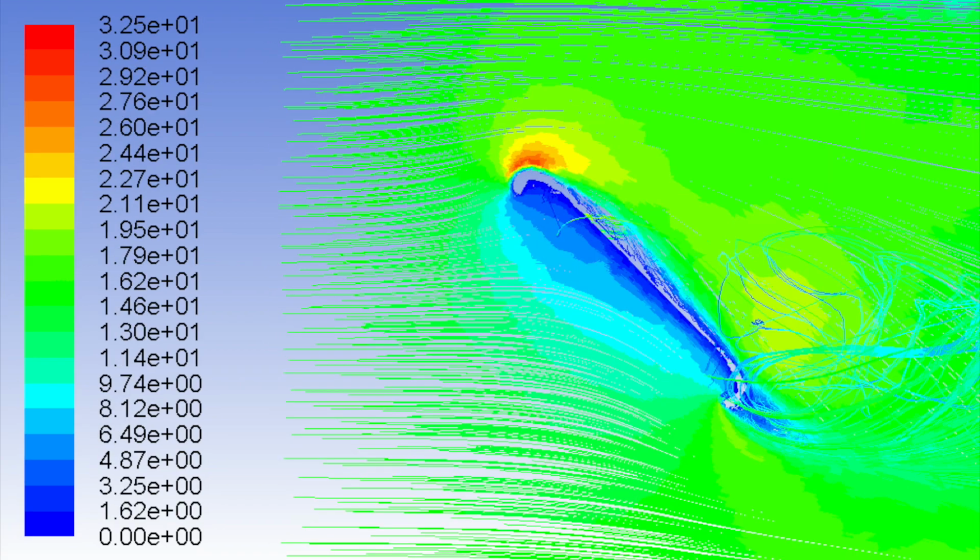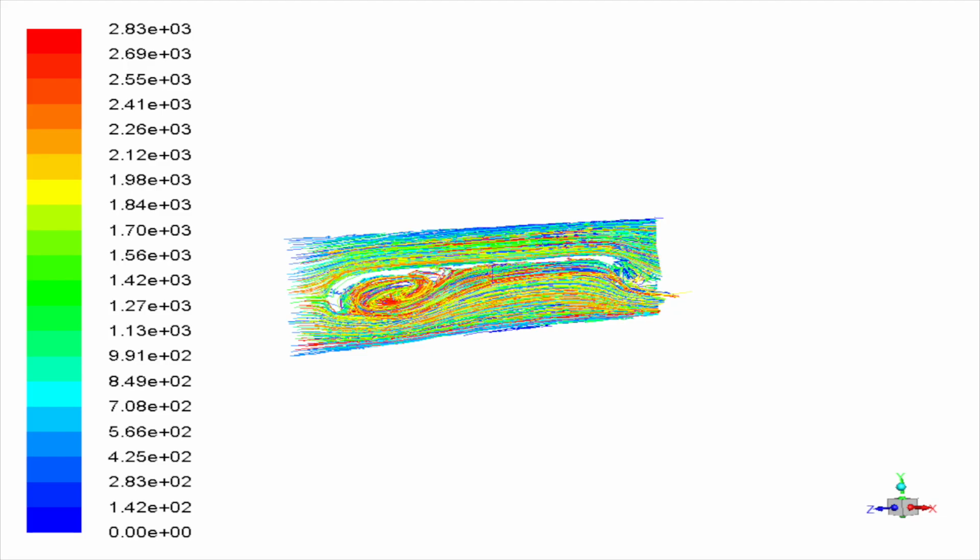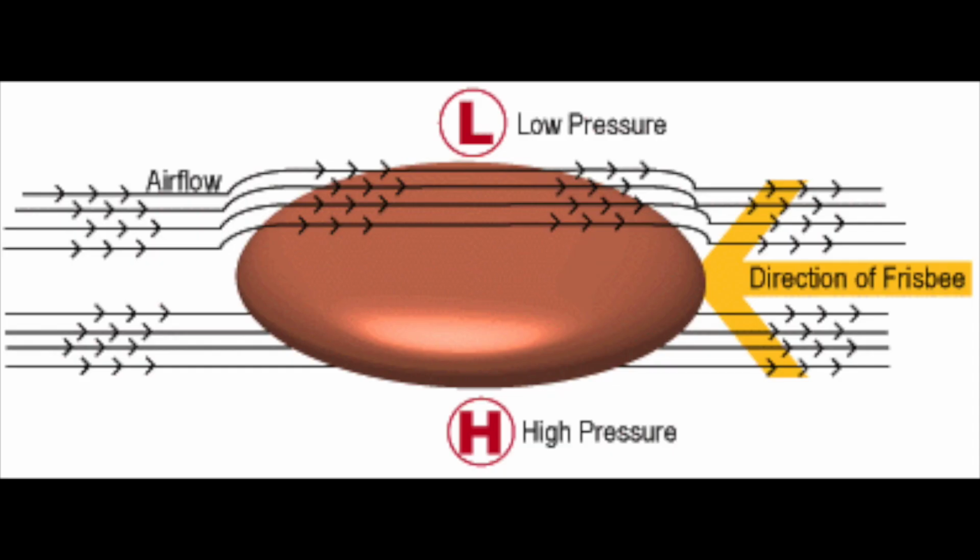The light dark blue lines represent the slow-moving air. At a release angle of 0 degrees, we can see that the air travels around the disc relatively evenly. The air above the disc is not deflected, as such lift is not generated. Looking closely at the diagram, one can see the currents that form underneath the disc. This creation of current creates drag in the system.